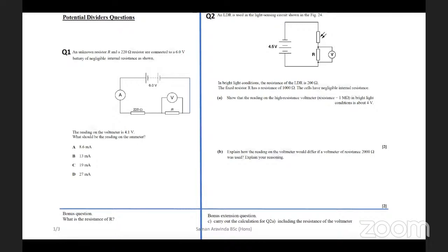So then the voltmeter reading will be low, no? Calculate it and see. Tell me how much is the value. It has to be lower because the total resistance will be lower. The total resistance of R and V will be less than 1000. Without even a calculation, you can say it is somewhat like 667.